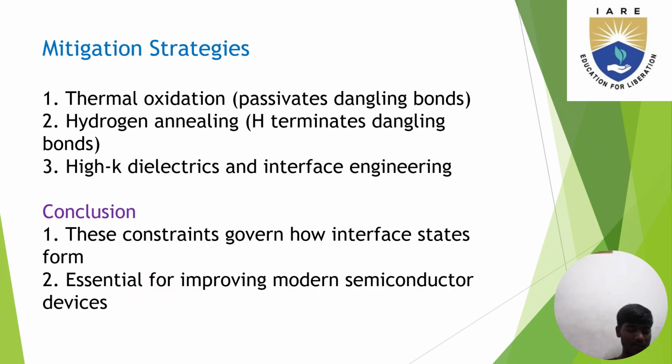Surface band bending. Dangling bond states create charge at the interface, which can cause the semiconductor's energy bands to bend up or down near the surface. This effect can lead to the formation of depletion or accumulation layers and affects the electrical response.